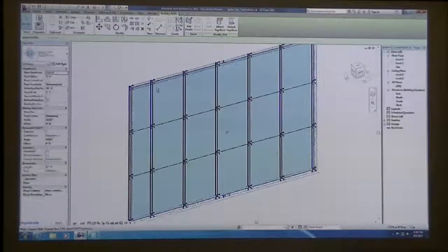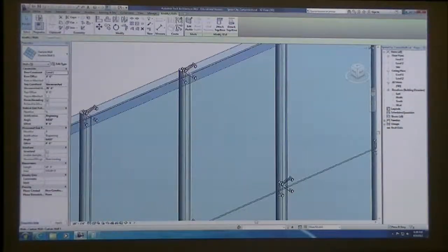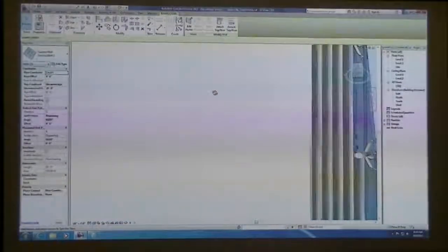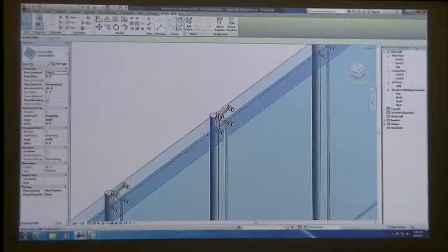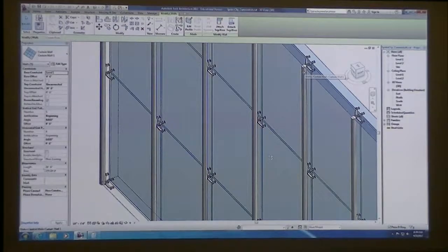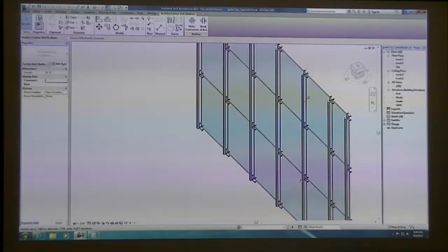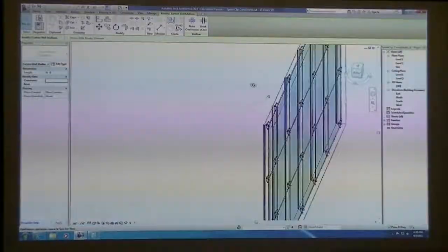But when we get into wanting to do a little more complex systems, there are some quick methods that we could use, and we have to tweak a few things in Revit so that we can actually get a spider clip system to work with a mullion structural backup. Typically a spider system has a vertical pipe behind it, and there might be some horizontal pipes every now and then. I'm not going to get into that detail, and of course they have cross bracing, and there's a lot of parts and pieces to the spider clip system.